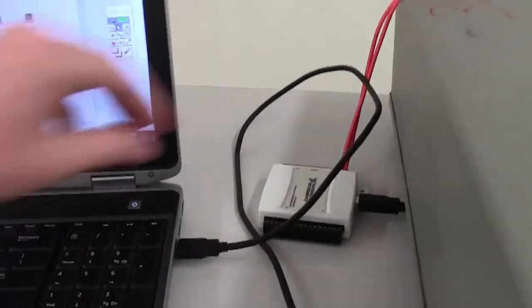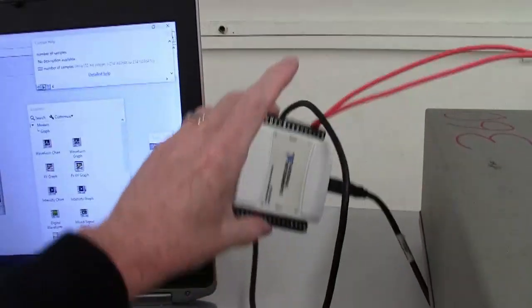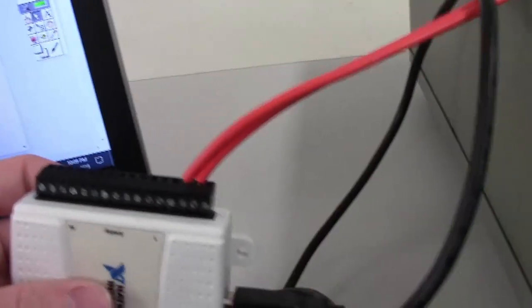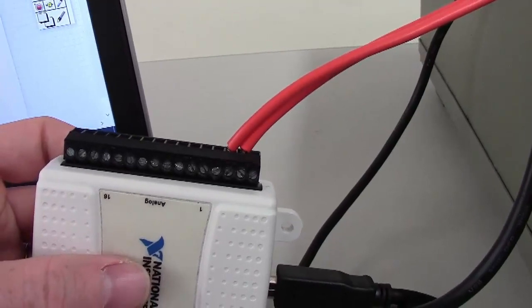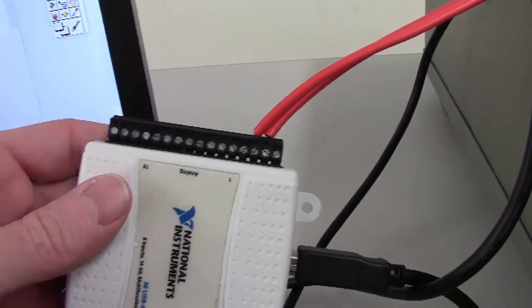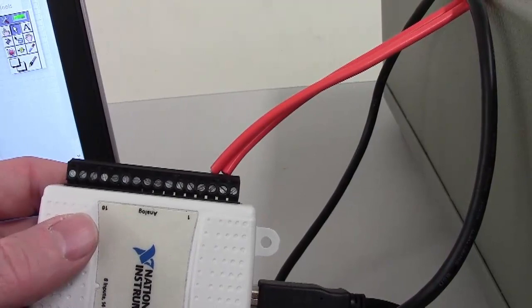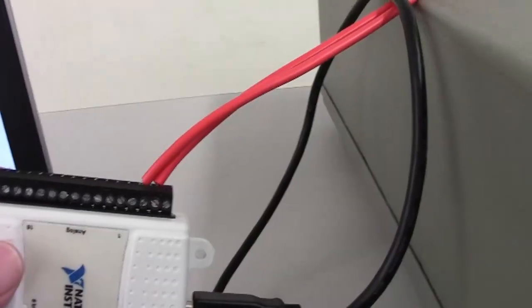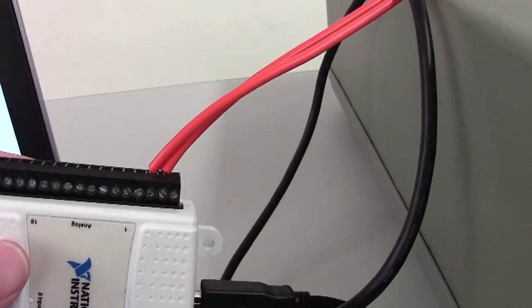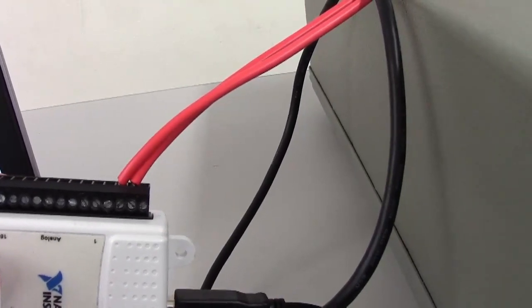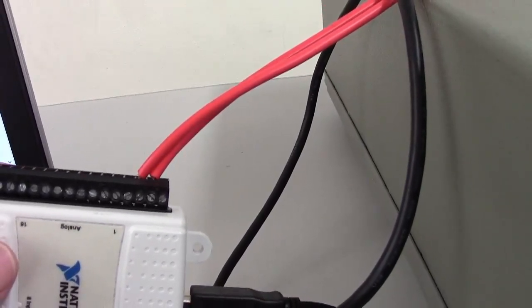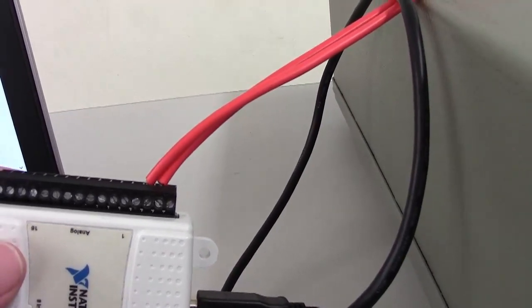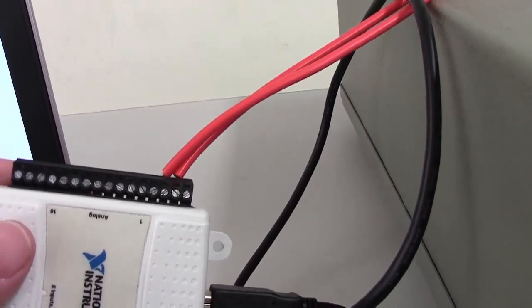Over here is the computer setup. Here's that DAC. And like I said, it's just simply plugged into my laptop via USB. And like we saw when we used our DAC assistant to configure this DAC, we were plugging our two leads into channels 2 and 3. I think it was positive into 2 and negative into 3. You can try to keep track of it if you want, but it's not too big of a deal. It's just going to be flipped in polarity if you get those switched around.